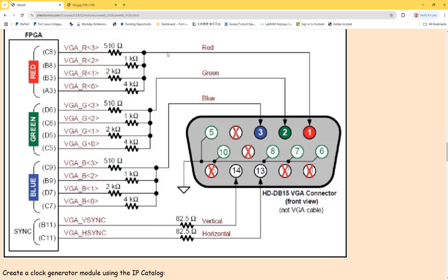How many of you are in my VLSI class? So you are not. Everyone else actually, right? So superposition, you got it. Just imagine there's a voltage source. I've got voltage sources V1, V2, V3, V4 connected to these ports. And the very first step of the superposition is what? Cancel out the other ones. Cancel or do what? Short. Short where? Yes. So for example, V1 only. Then V2, V3, V4 need to be shorted to ground.